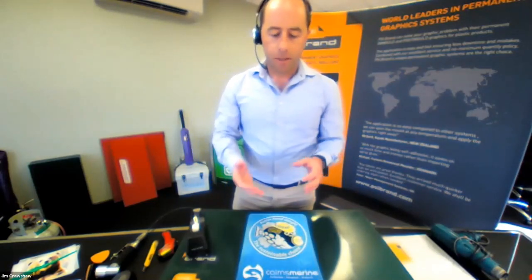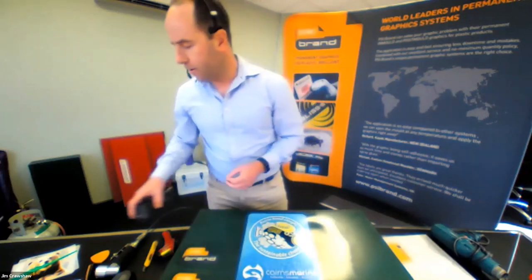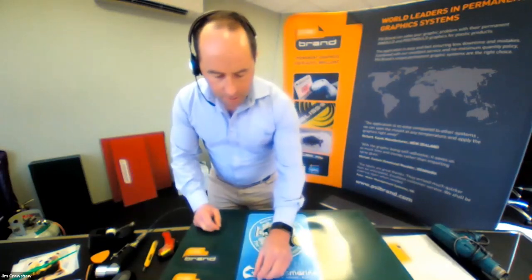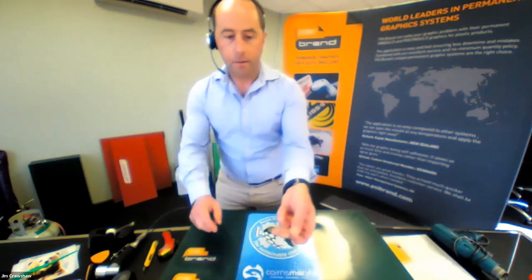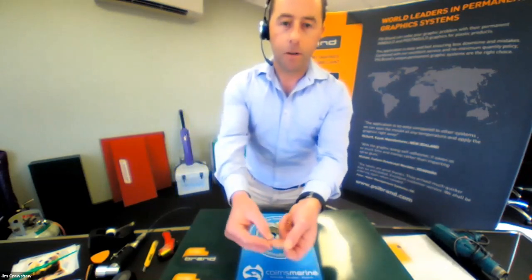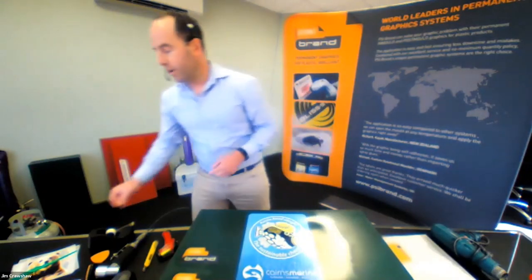Like I say, you do this test on your very first molding, perhaps on a scrap piece, just to establish that you've got your parameters right, because some plastics you need to go hotter, such as high densities. So just to give you that confidence that you've got great adhesion. Then I'm just grabbing the other piece of tape and pulling it away like this here. And if I've got any of the graphic left over on this tape here, that indicates poor transfer.